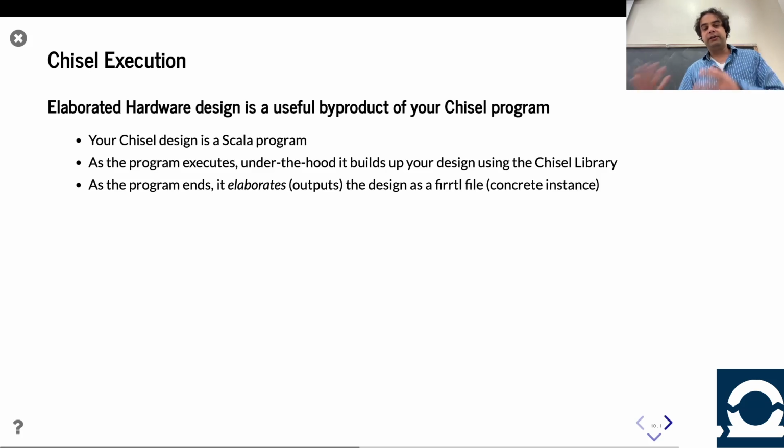So I keep saying over and over again, your Chisel design is a valid Scala program. All these things we keep talking about, like a module or a wire or a mux, all of those things are actually components in a Chisel library, and the Chisel library is just a Scala library. And so what's happening is, as your program's running, under the hood, it's building things up. It's instantiating things, connecting them. And then at the end, your program does what's called elaboration. That is, it goes through this in-memory representation of your design, and it turns it into a circuit. And that's sort of the Verilog file we're talking about, right? And so you may have noticed earlier I was talking about how you can't just have hardware by itself, it needs to be inside of a module. Now you understand why it needs to be in a module.